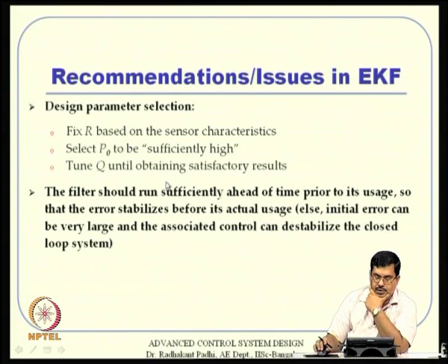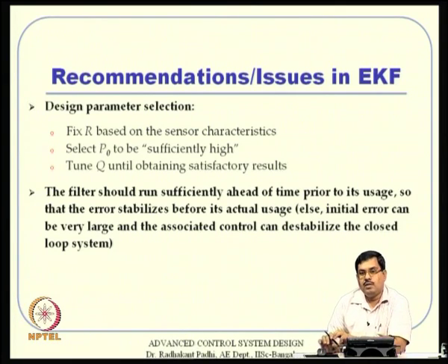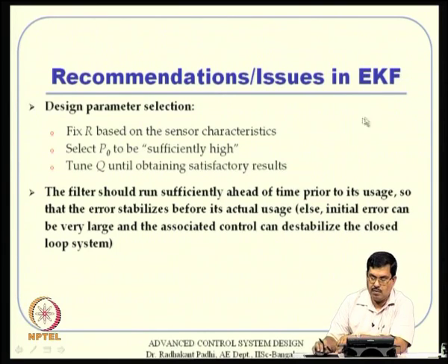Second issue: as I told, this EKF will go through initial large transients. Initially it will go through large transients, and then ultimately it will settle, and after that the error will be small. So, obviously you do not want to use these transient values, which are erroneous anyway. So, what you have to do is run the filter sufficiently ahead of time prior to its usage, so that the error stabilizes before its actual usage.